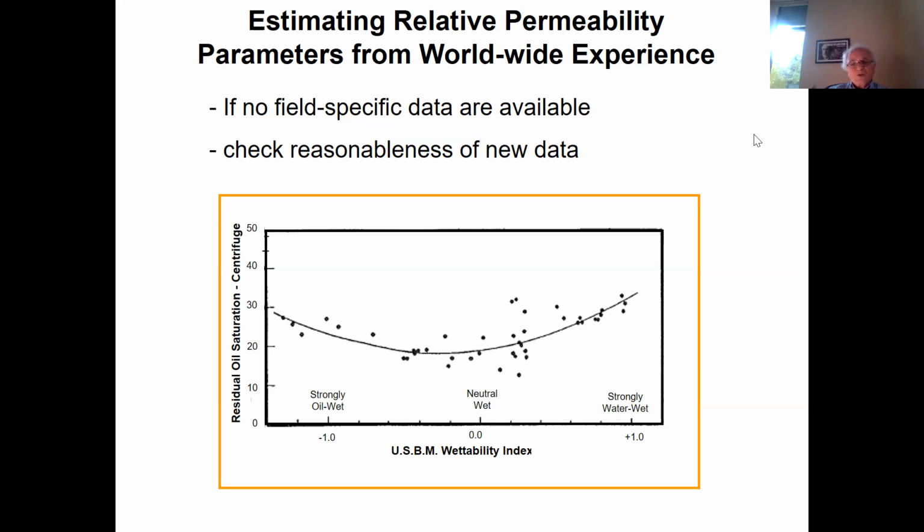Now, what you're showing here also is that there is really no systematic effect of wettability, and a lot of the argument in the literature is that the more water wetting you do, the better. To me, actually, this is an indication. Suppose these results are okay. That means the statement we often see in the literature, that there is somehow a preference for water wetting, maybe for mobility control, which is different. But in terms of recovery, that emphasis in the literature may not be valid.